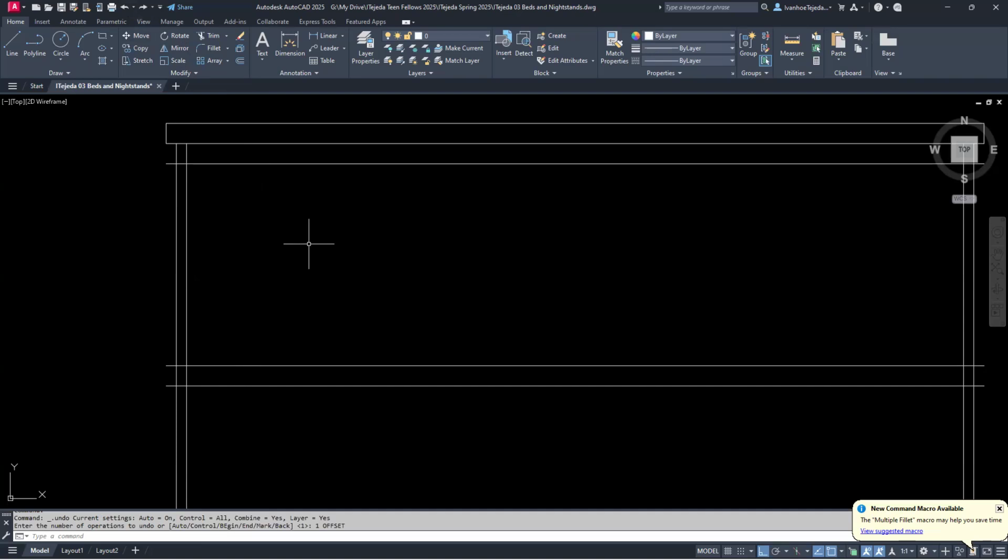And I can draw a line, so I'll type L, enter. From this point, notice how I pause here for a second, finds the intersection. I start moving it over to my right, and as it's moving over, I take my hand off the mouse and I type in 5 and enter. And it gives me that line segment that I wanted.